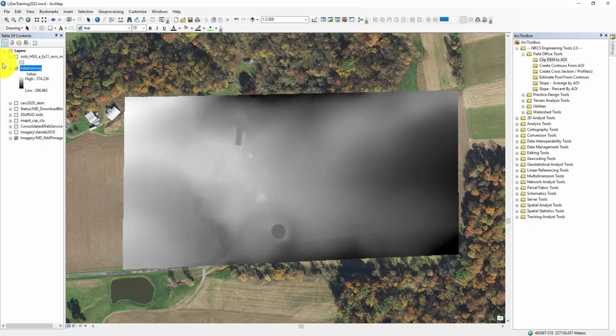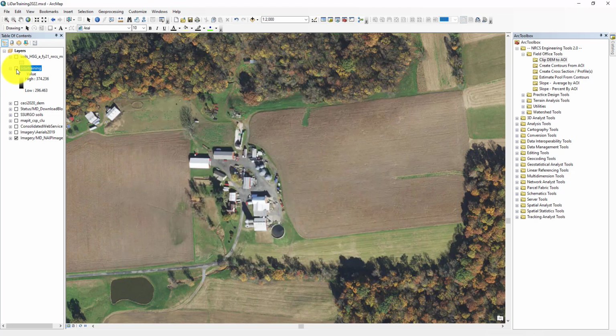Once you've completed that process, you can go ahead and close down ArcGIS, unless you have to make a watershed or something like that, but this is specifically geared towards just grabbing that DEM file to import into Civil 3D. So we can now close down ArcGIS.